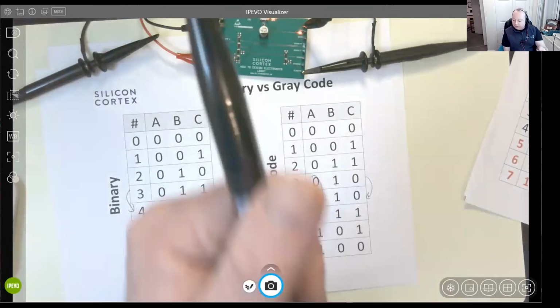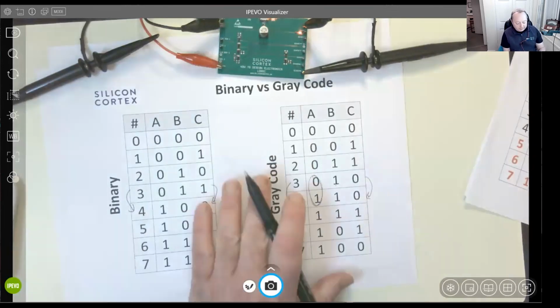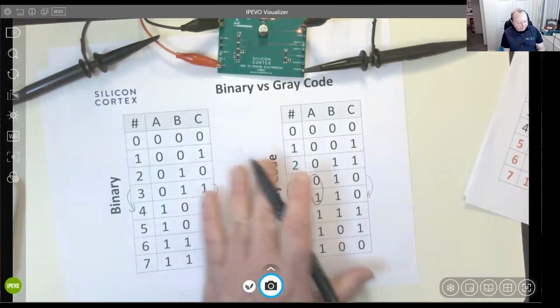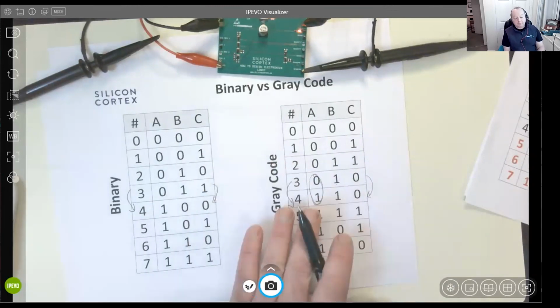On the subject of trying to solve this ringing, on a medical product I've been working on recently, we've had a devil of a job with Maxim, who are meant to be a very respectable company. They actually capacitively loaded their data ports to try and reduce EMC.